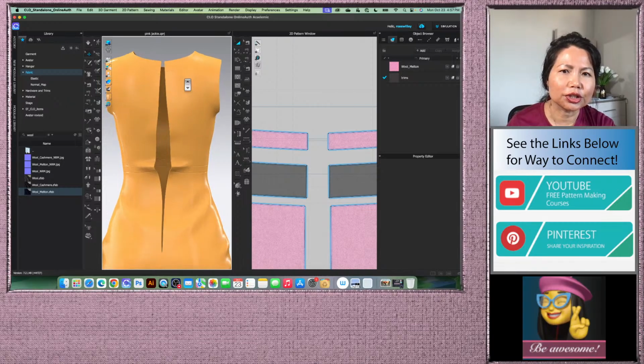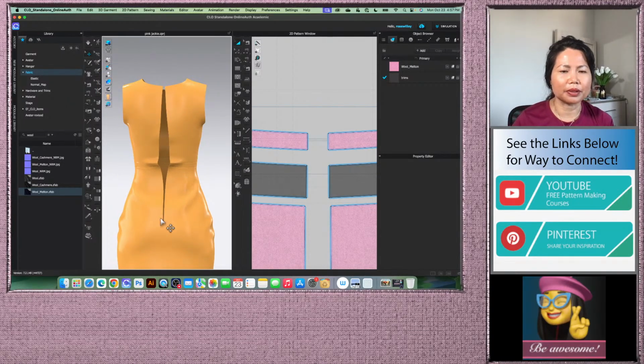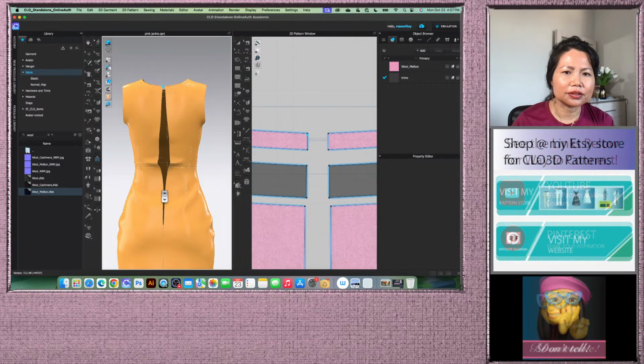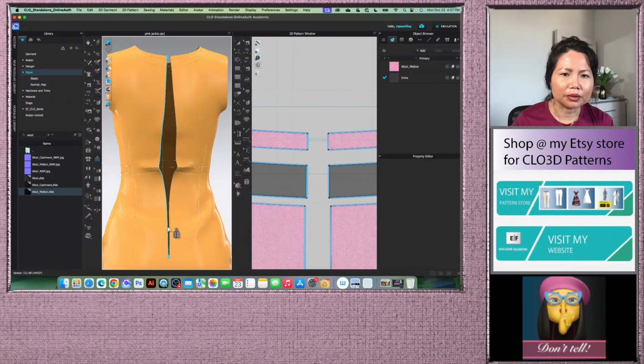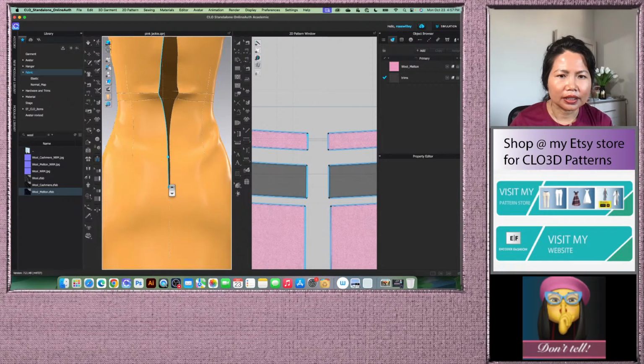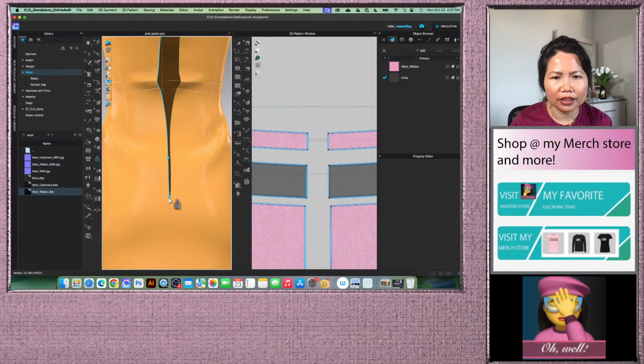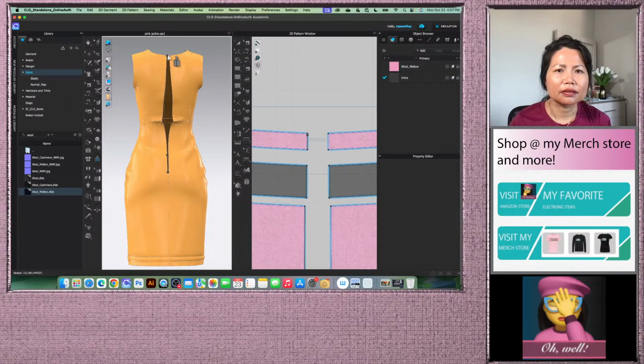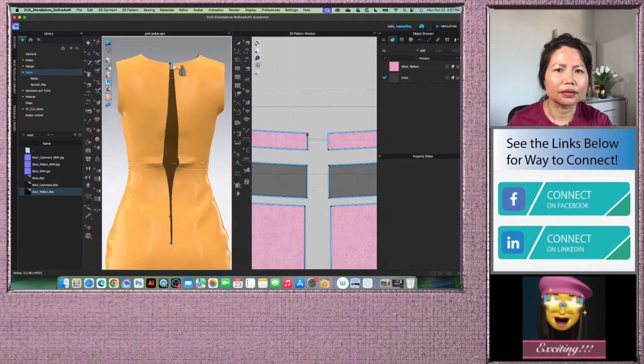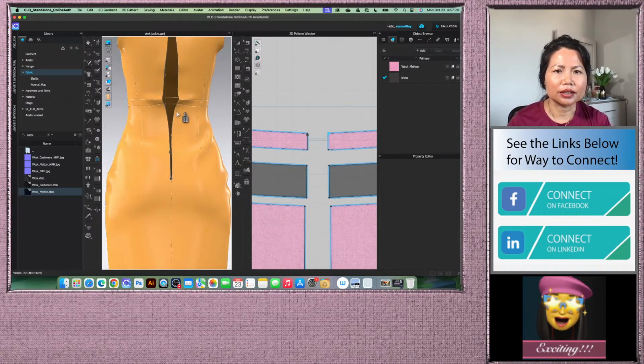Alright, so now I'm going to sew the zipper. So we'll use the zipper tool here, click once right there to sew to. And then I'm going to zoom in closely. And when it's almost reached right there, double click to end the zipper. We'll continue from here. Let's zoom in. I'm gonna start right here, click once to start, and then I'm gonna sew down here.